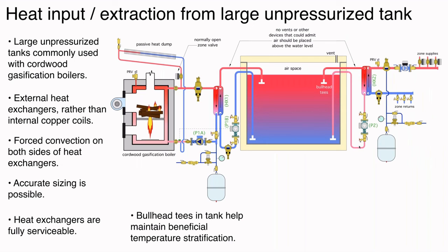This is the alternative to the copper coils in the tank, the large thermal storage tank. We're using external brazed plate heat exchangers. Definitely stainless steel circulators because this is an open vented tank here. This is not a closed system.